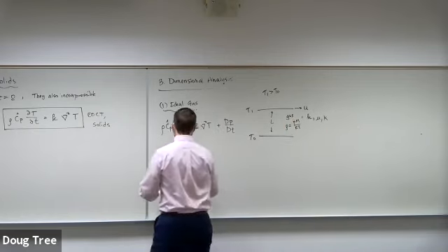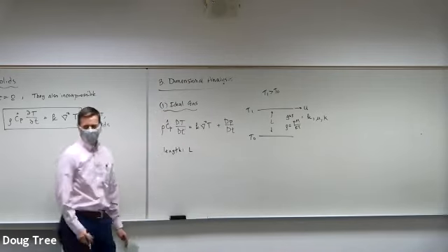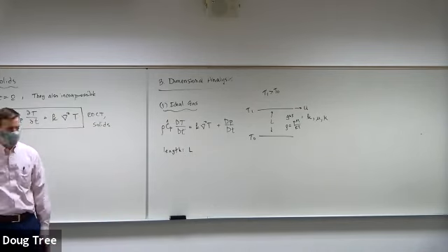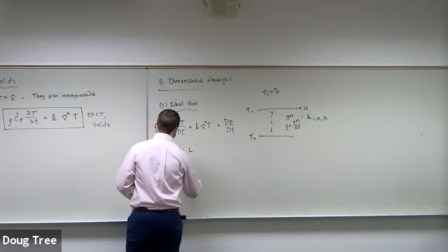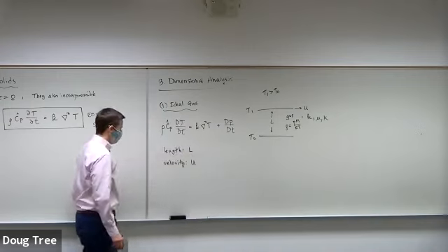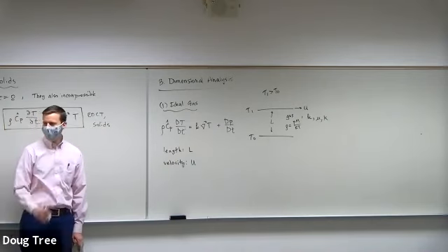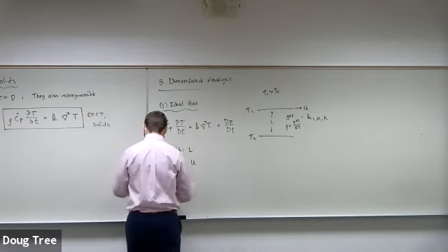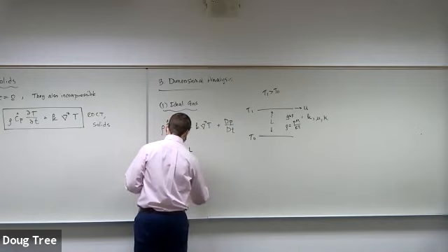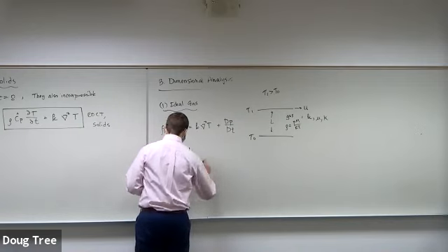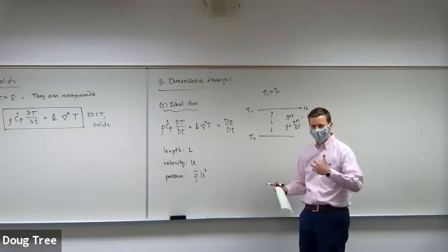So here we can find a length. That one's usually the easiest. It's like the size of the problem in some sense. Here it's the gap height, L. We're going to have a velocity, which will be U. The velocity we're going to use to get our time, right? So that's how we're going to get a time scale. Then we're going to pick a pressure scale, which I'm going to make rho U squared. But this is really the same as fixing our mass scale.